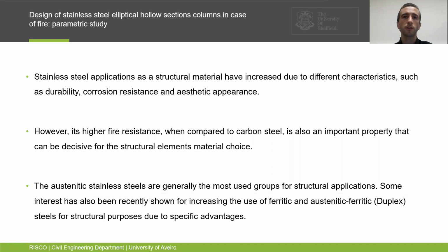The most common stainless steel grade is the austenitic, but recently some interest has also been shown for the use of ferritic and duplex steels due to the specific advantages like the lower percentage of nickel of the ferritic grade, which reduces its price, and the good resistance to wear and stress corrosion cracking of the duplex grade.